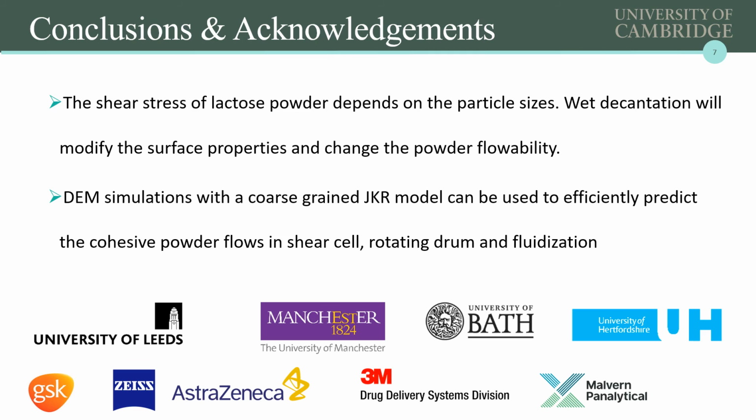So in conclusion, the shear stress of lactose powders depends on the particle size. The wet decantation will modify the surface property and change the powder flowabilities. After calibration, the DEM simulation with a coarse-grained JKR model can be used to efficiently predict the cohesive particle flows.